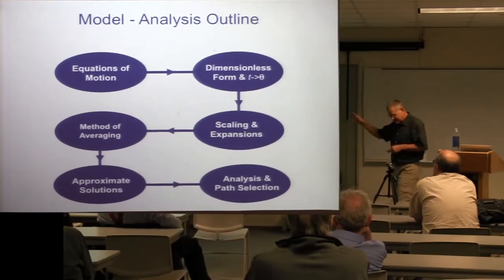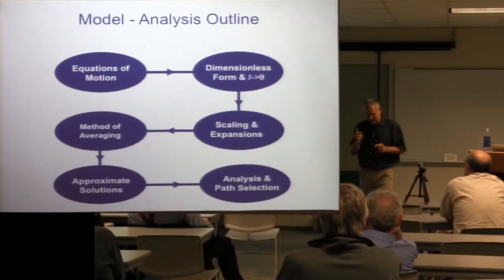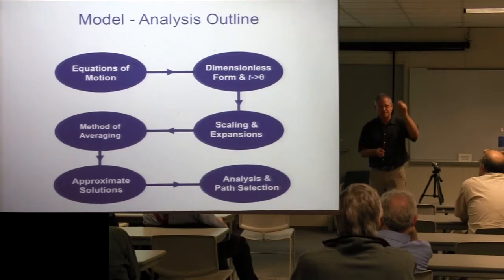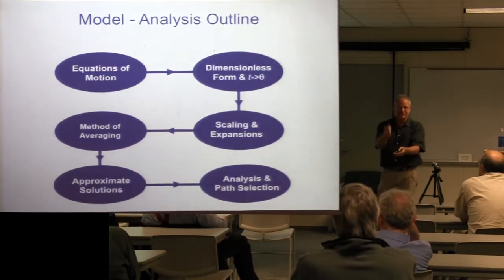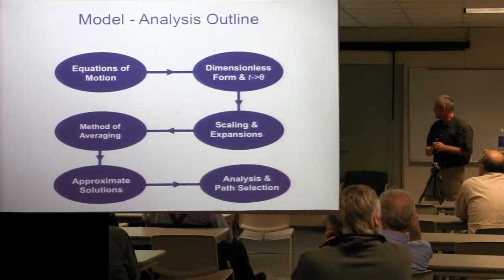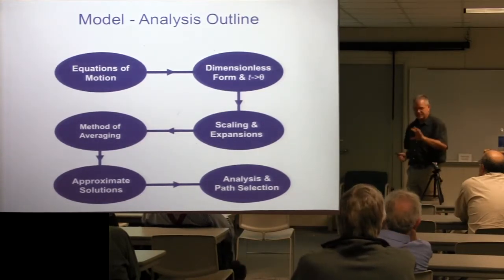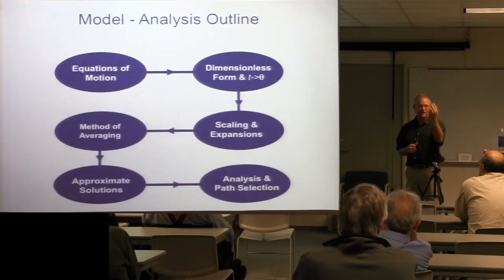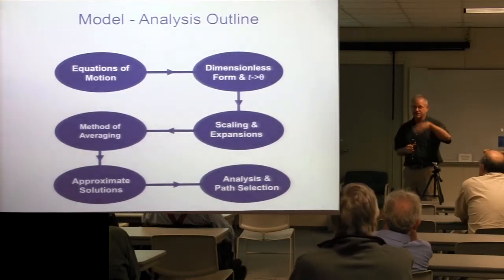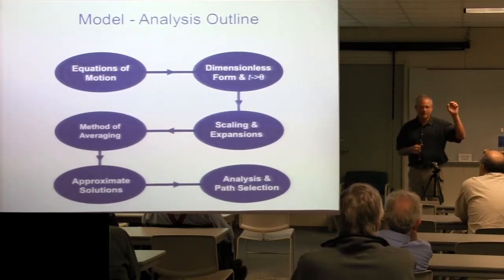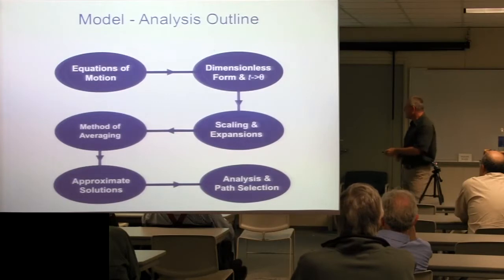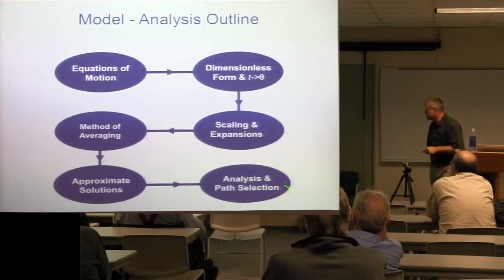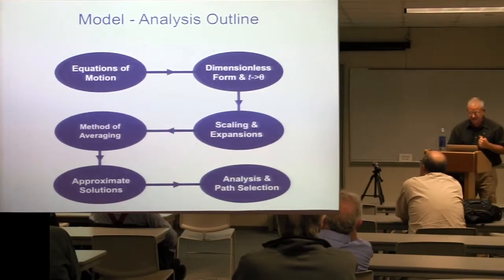It turns out that the scaling on these things, because they're tuned at all engine speeds, you want them to be lightly damped. Remember that valley? You want them to be lightly damped. You can tune them near resonance. If you look at the parameters, say the amplitudes of the torques, when you scale the equations, you scale those torques by the kinetic energy of the whole system. That's a small parameter. You have small damping, small forcing, small inertia ratio, that works out the scaling, so you can apply a standard method of averaging, and you can use that to analyze the system.